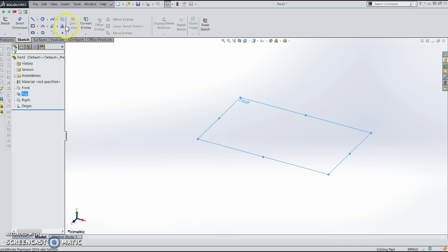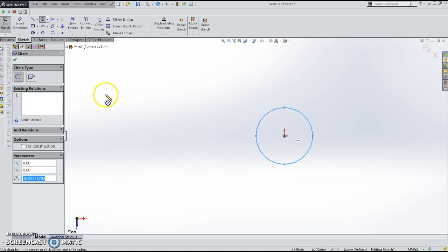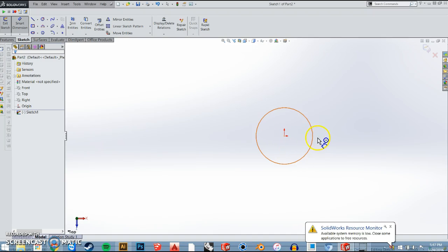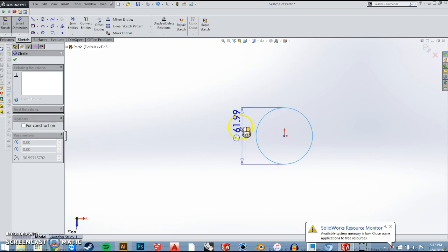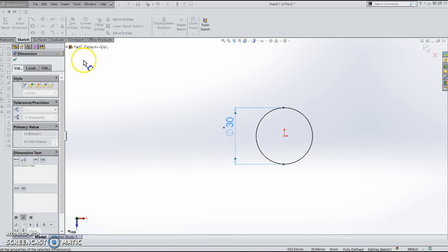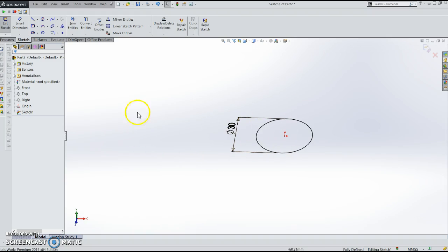So sketch on the top plane here. So it's normal to. Put a dimension on here. Again, I hit the letter S to get that shortcut menu. It's a very helpful tool. It's in millimeters, so to specify, I can either type 3 centimeters, or I can just put 30. The sketch is black. It's good to have black sketches in SOLIDWORKS, that way you make sure that they're all defined and not going to move around. So I can exit this sketch.